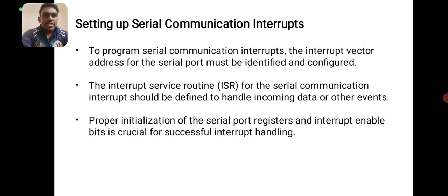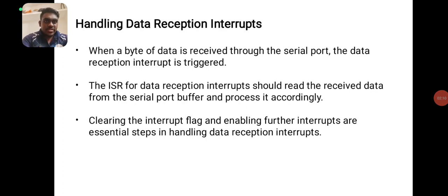Setting up serial communication interrupts. To program serial communication interrupts, the interrupt vector addresses of the serial port must be configured. The interrupt service routine, ISR, for the serial communication interrupts should be designed to handle incoming data or other events. Proper initialization of serial port registers and interrupt enable bits is crucial for successful interrupt handling.